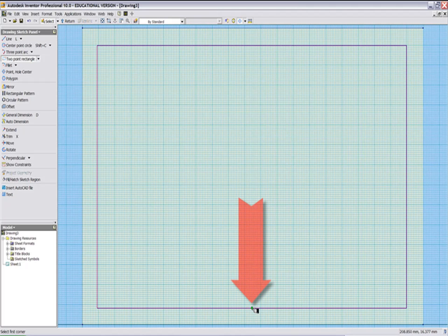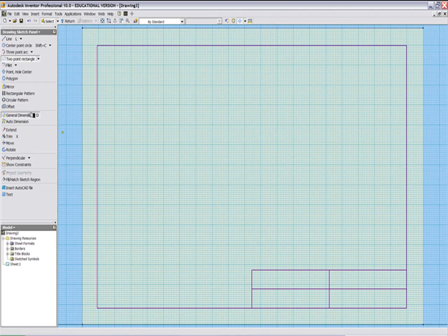While we're at it, hunt for the midpoint on that line, click and click on the right hand side, and we've created a rectangle that's going to represent our title block. I'm going to find the midpoint here and drag down to the midpoint there, click again, snap to that corner, snap to that junction. I'll settle for that as a combined border and title box.